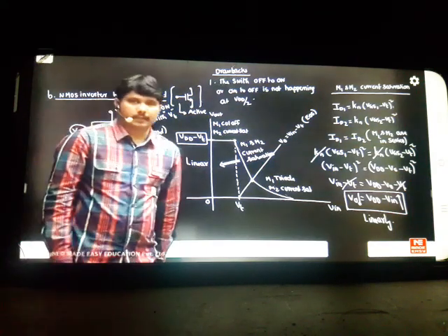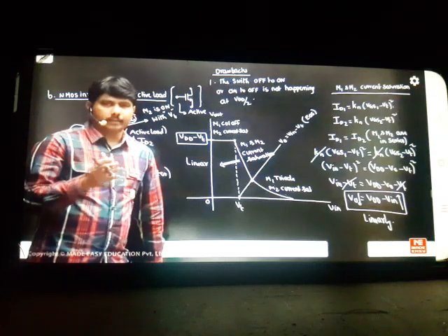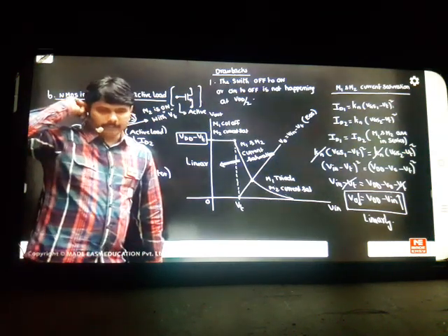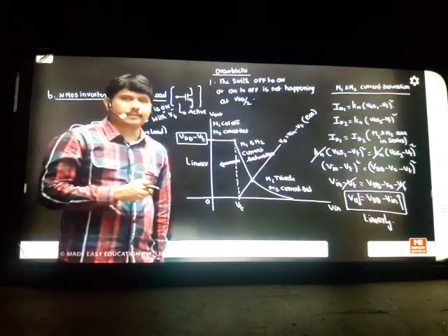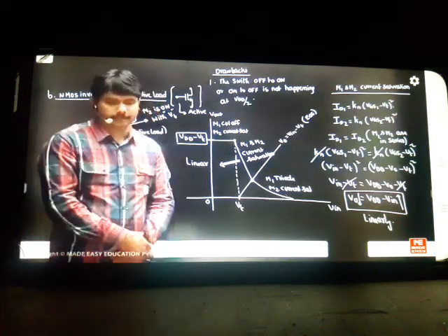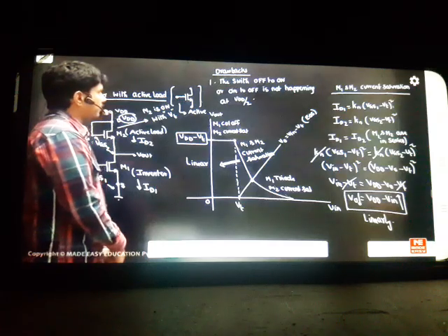Threshold voltages are generally different, slightly mismatched, but theoretically we said both are the same, and we'll study that in the classes. Okay? We'll say slightly different, like the beta story in BJTs. Yes, the betas, and your threshold voltage can change slightly, KNs will change, slightly mismatched. They're all called mismatching parameters, slightly different.